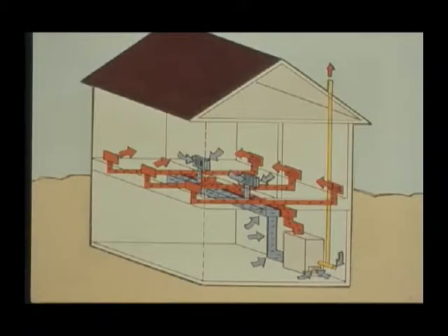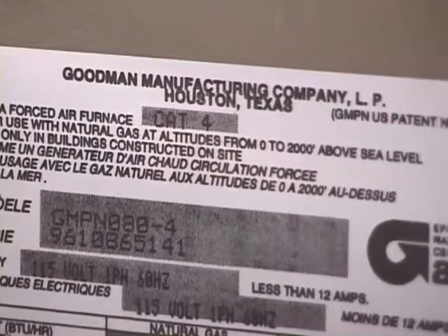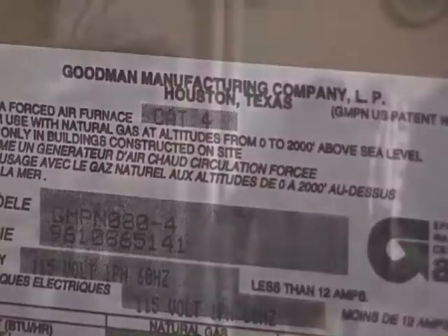Since the venting system is largely isolated from the house, especially when using two pipes, the common spillage and backdrafting problems experienced by Category 1 systems rarely occur with Category 3 and 4 systems. Nonetheless, manufacturers' instructions and tables must be carefully followed, notably the common requirement that the total equivalent length or friction resistance of the two pipes be roughly the same.